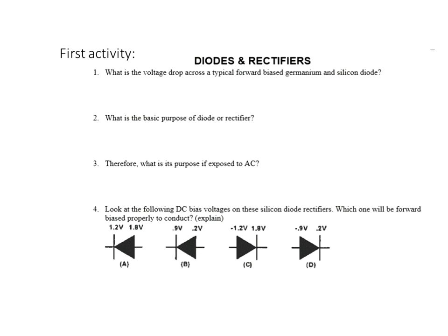What you learned in second quarter when you first started working with p-n junctions was that there's something called a diode. A diode is sometimes called a rectifier. It's made out of p and n materials put together, and when you put them together, you get something in between called a depletion region. The depletion region looks like an insulator. How many volts do I need to apply to the anode to make the depletion region go away and cause the diode to begin to conduct?